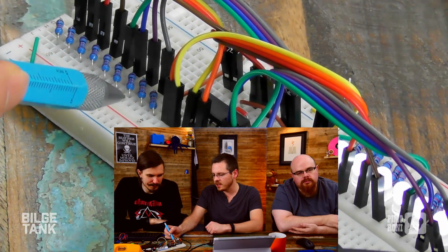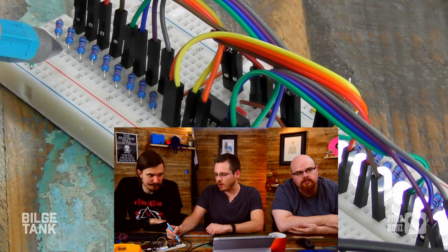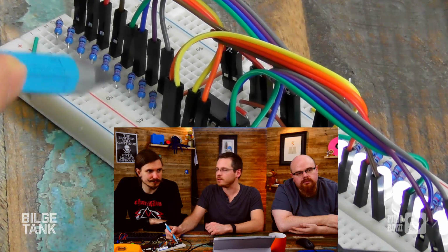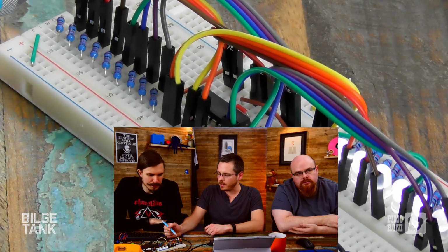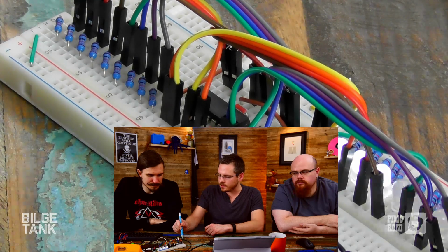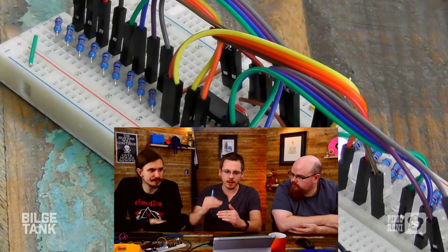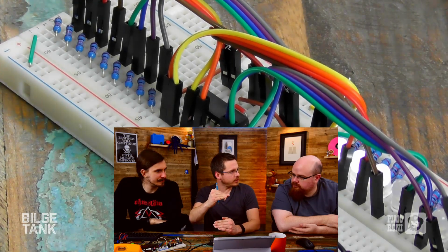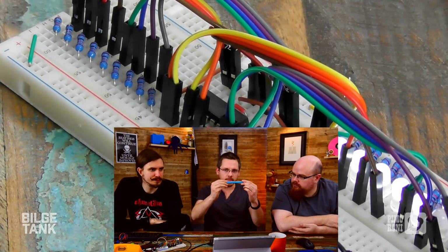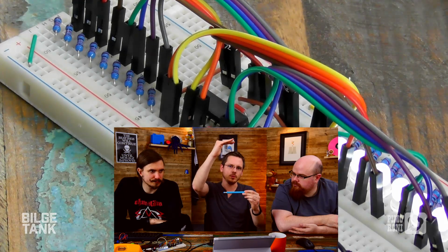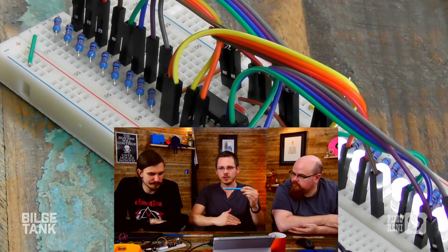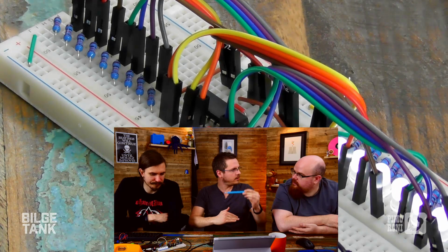Which it isn't, but if it were, you'd essentially read roughly 1 volt, 2 volt, 3 volt, 4 volt as you stepped up the ladder. And that means we've actually got 8 discrete increments of voltage, and that gives us our resolution essentially on the ADC. So where I was holding the pen up saying that's 2.5 volts, and Paul was like at VCC and ground, on ours we've got 8 pens. 8 pens. All the way in between.